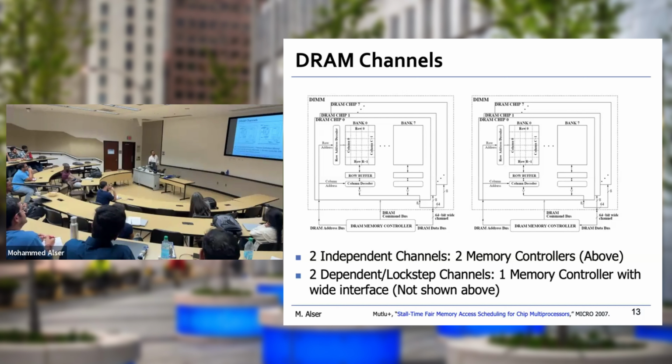However, it's expensive because we first need to change the CPU itself, because the memory controller is located in the CPU. If we need to add 2 memory controllers, that is an overhead to the area of the silicon itself. So we need to change the architecture of the CPU to do that. And then we need 2 physical channels to communicate with the DIMMs. Is that clear?